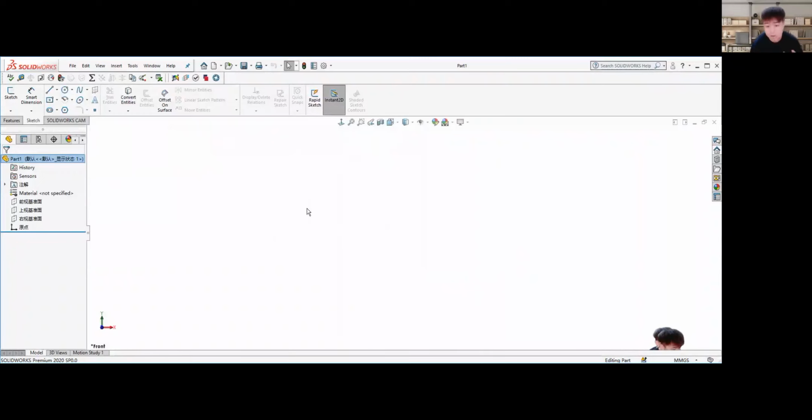And we're going to make an example in the sketch part. If you want to design a part, first you need to sketch. Sketch it at a 2D level, and then you can transform it into a 3D level. Let's click on sketch, and you can see some functions for the sketch. We can use a line, circle, spline, center triangle, arcs, ellipse, anything we want.